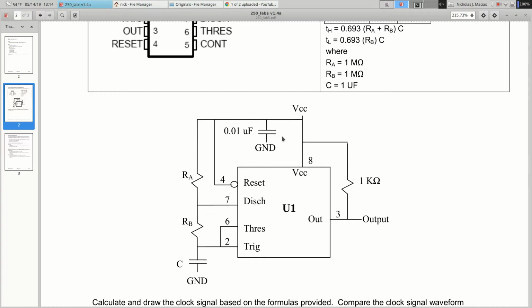And we'll use this in 270, and it'll really be important in 270 because we'll be driving motors with our circuits, and motors produce a lot of electrical noise. If you leave that off on this circuit, it's going to work great. Okay, but you may as well put it in because it's good practice. So that's just to clean up the power supply.